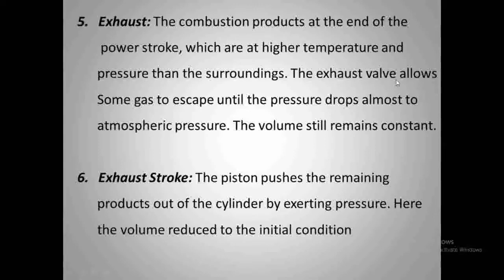The pressure inside is higher than the pressure outside, so the products will go out until the pressure drops almost to atmospheric pressure. But during the process, the volume remains constant. There is no change in the volume of the chamber, only some amount of the combustion products will go out through the exhaust valve.